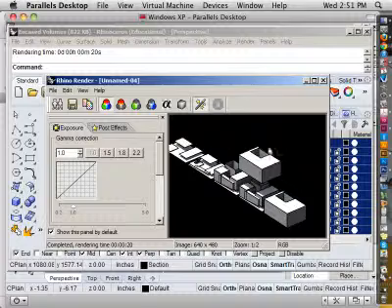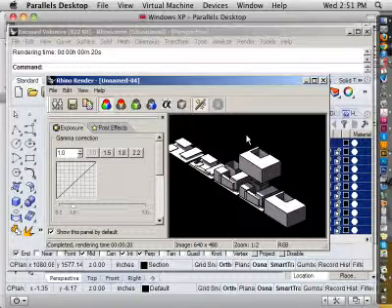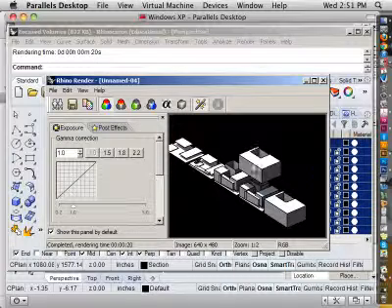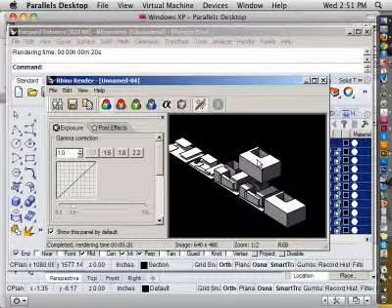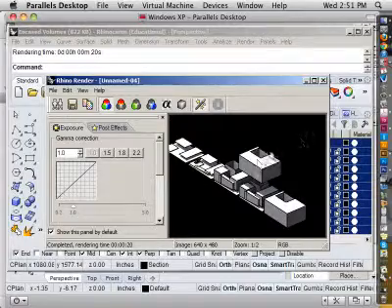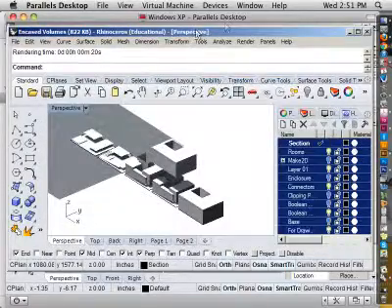And make sure you do this at a high enough resolution that you're going to be able to get it to look right on your screen. Otherwise, you'll want to do the Make 2D so that you can control the thickness or the line weights of the outlines of the boxes. Right now, if I put this on my board, it's going to look really pixelated because it's a really low resolution rendering. So remember that you set those under render properties,